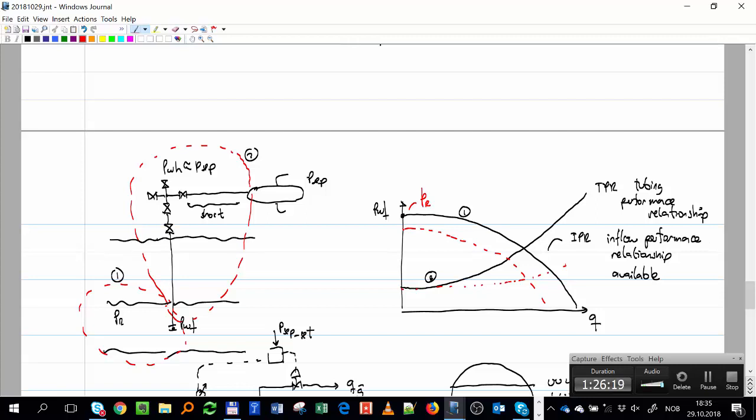Let's say that I have just gas, and I stop the flow of gas. This curve I calculate just by looking at this system. When I have no flow, this pressure will be constant: the separator pressure plus the hydrostatic column of gas that I have in my flow. So that will be P separator plus rho average times g times TVD, true vertical depth.